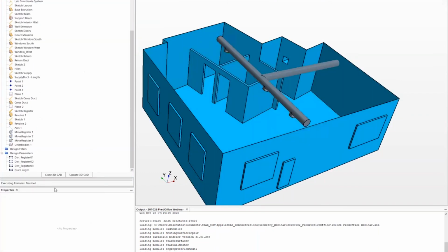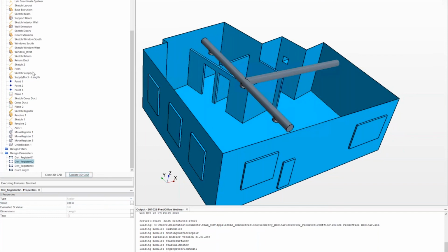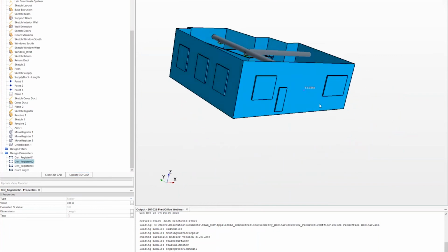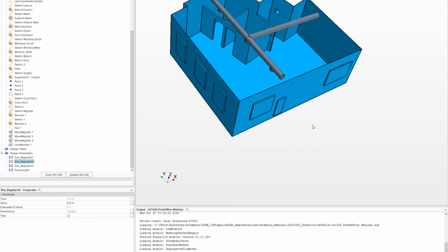And the thing about this, because it's all parameterized, we can always go through here at any time, even in the CAD part, and make a couple adjustments to this. Right here, you can adjust any of these variables that we want and hit Update CAD. There were yellow triangles that showed up here that show that those are parts that needed to be updated. But with Update CAD, one click, it goes through and re-updates everything that you did with the new parameters.